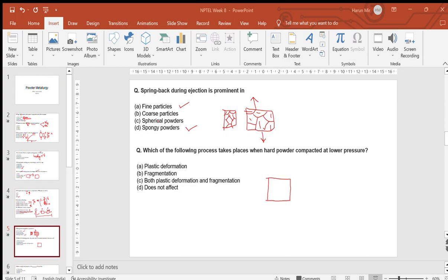Third one, I guess. Over excess. Right, because one of the options is that excess binder is being used. What is the required volume? It is 40%. So you are using actually greater than the binder volume for a mixture. If you have excess, there is separation of the powder and the binder, because there will be no interactions between particle and particle. Because of the excess binder, we do not have enough particle interactions, which are required with the help of a binder. So this is the right option.